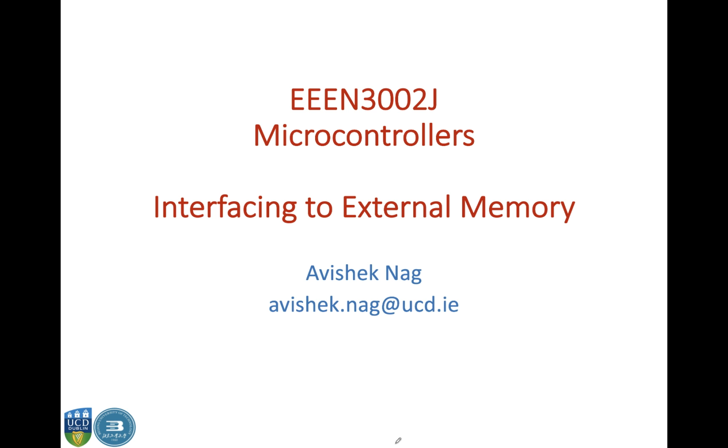Many times before, we discussed several instructions like MOVX, etc., or MOVC. So this X stands for external. This instruction is mostly to fetch data from an external memory or to send data to an external memory. Then MOVC is associated with sending and bringing data from external code memory, etc. So in this lecture you would be able to appreciate more of these things.